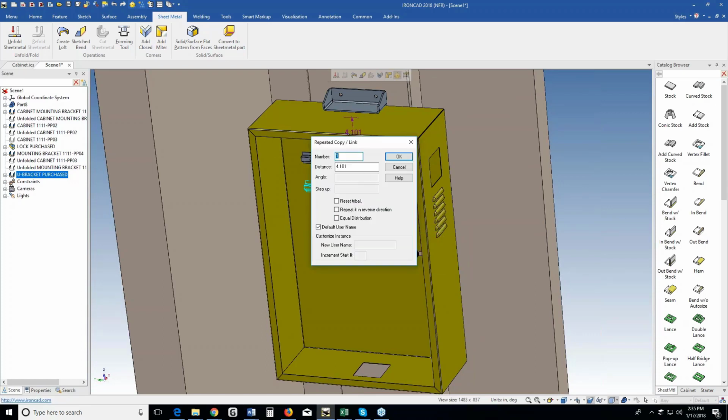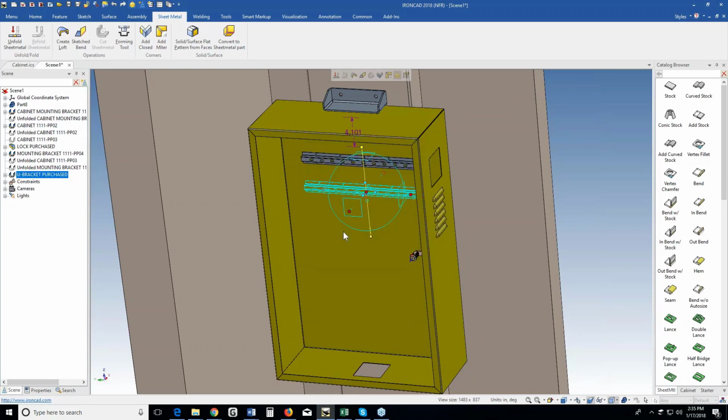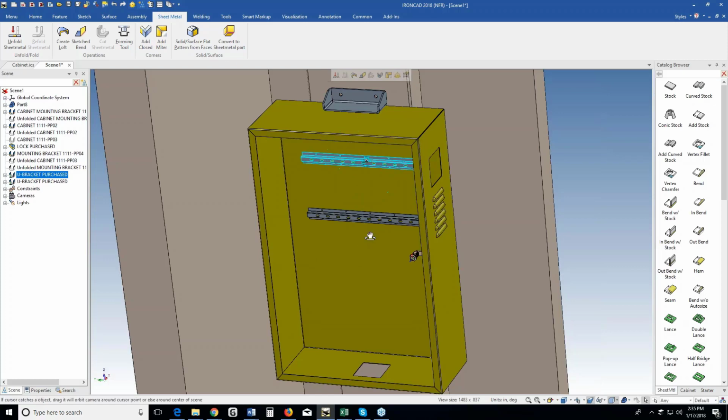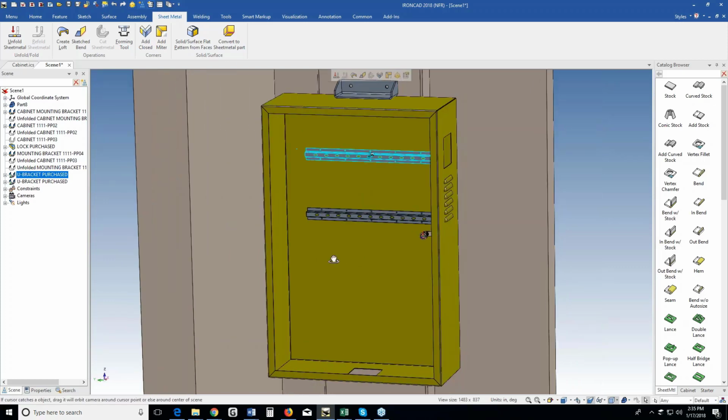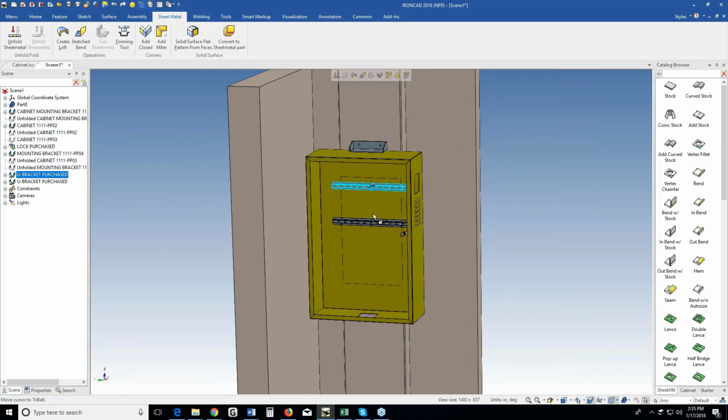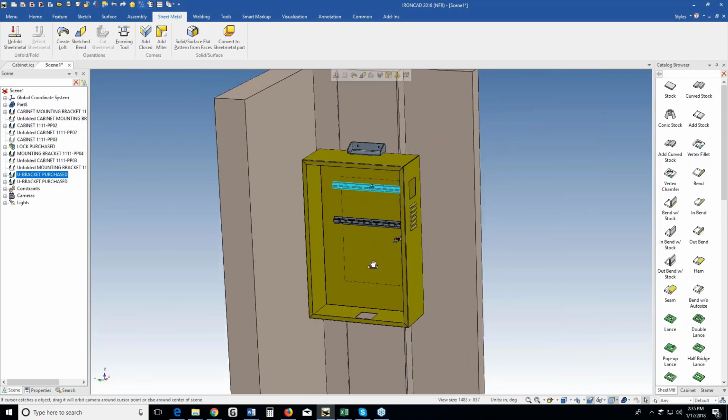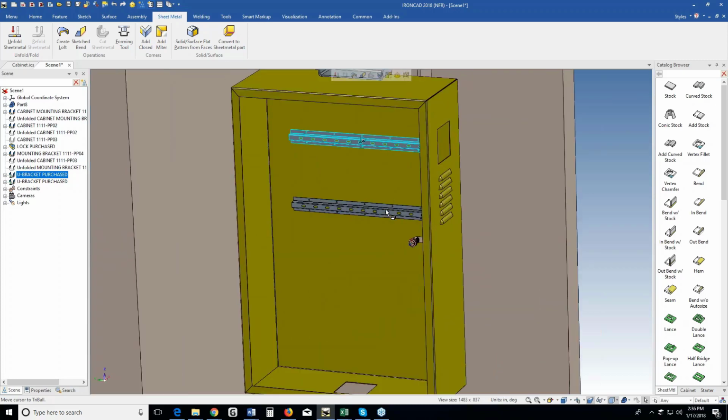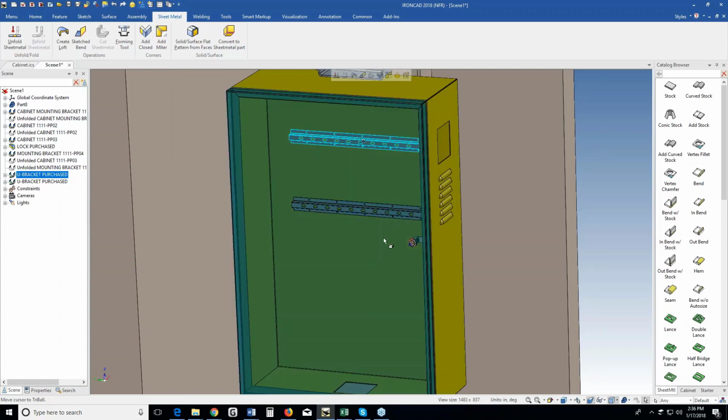And we'll do a link copy so that we have a couple of mounting brackets for anything that we would want to put inside of the assembly. So the sketch bend tool is very handy for when somebody sends you a flat pattern, but they don't send you any other information. If you want to do an oddball bend of some sort where you just want to put a line across a flat pattern, a flat part, you can do that very easily.